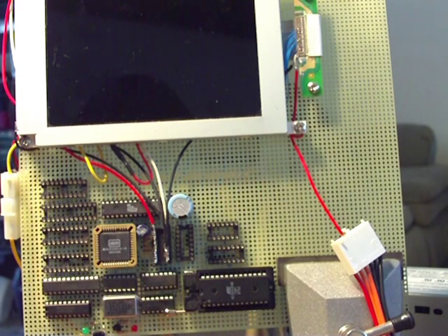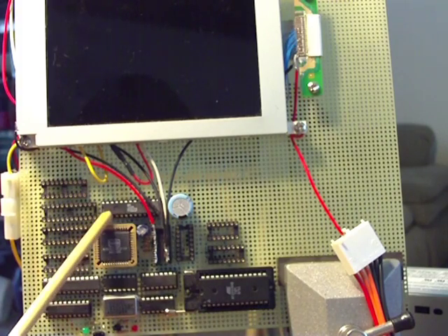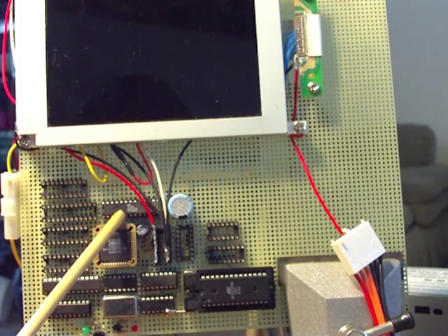I'm going to do is get the 6502 that can run at 3 volts, and I'm going to switch all the F series logic to HC, which can run at 3 volts no problem. I'll get a 3 volt crystal, and I'm going to get a 128K by 8. I'm only going to use a quarter of that,